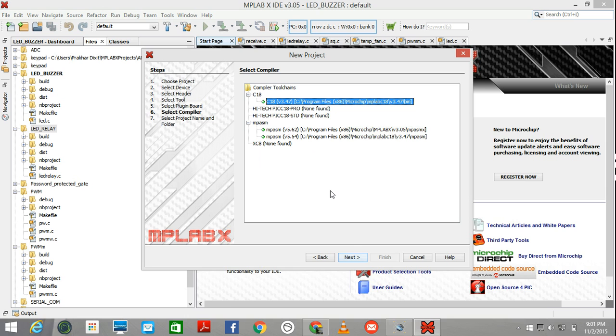When you download MPLAB X, you're actually going to have to download a C18 compiler as well. This does not come with the setup of MPLAB X. You have to download it separately. So I'm just going to be uploading this on my Google Drive anyway: all three things, the setup of C18, the setup of the microcontroller, and the setup for Proteus.